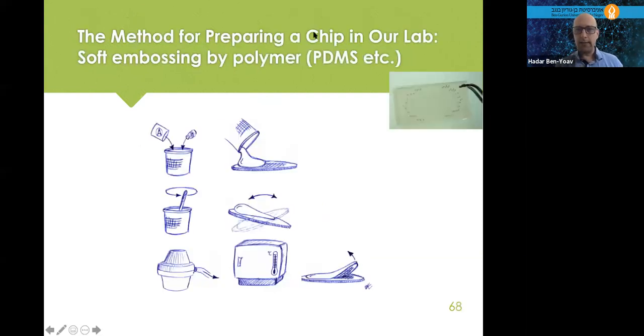So this is an example of how you actually do photolithography. The first part is making or fabricating. You have a substrate with a photoresist layer here. Now, instead of putting gold, because that's for electrodes, we are leaving the photoresist here as kind of a hump.